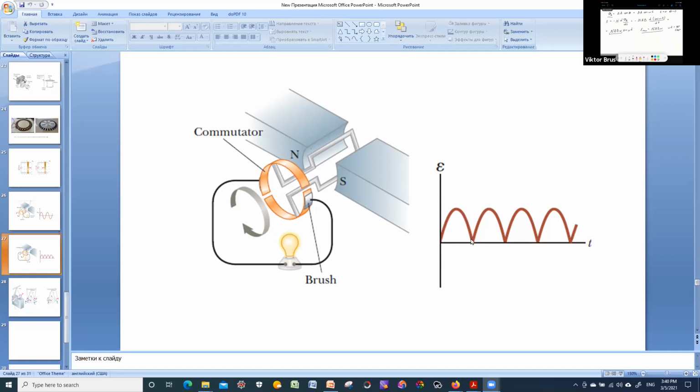And that's why we never get negative parts of the signal. We have the initial connection, we have a positive electromotive force, which is changing sinusoidally until reaching its minimum value, and instead of going down like the normal signal from an AC generator, because of the presence of this commutator, the negative polarity is kind of flipped over because of touching different terminals of the rotating frame.